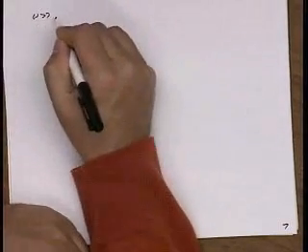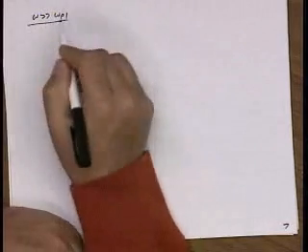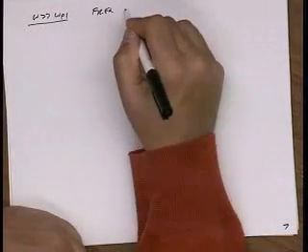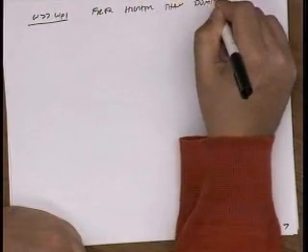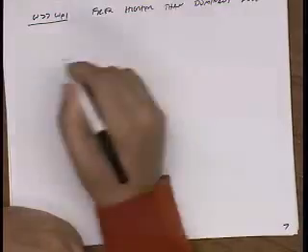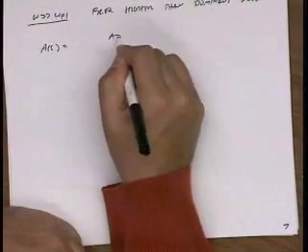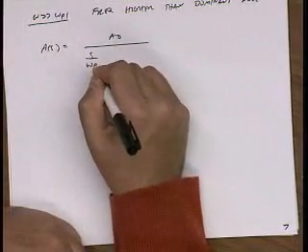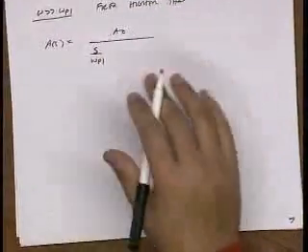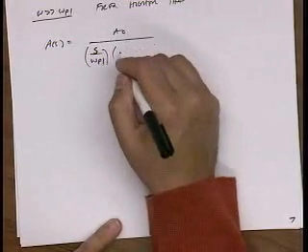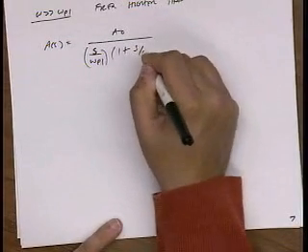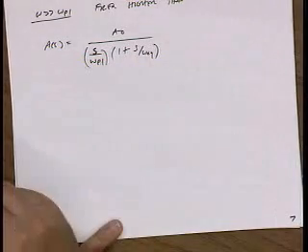Okay, so now let's look at frequencies much higher than the dominant pole. In which case, I know from our previous discussion that this is going to be the contribution of the dominant pole, right? We neglect the term 1. And then we're going to get a contribution from this equivalent pole.